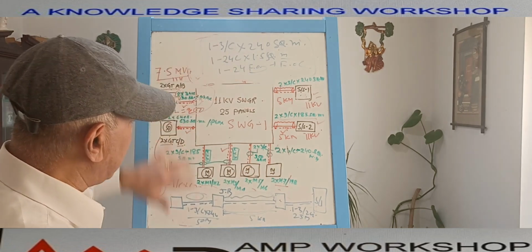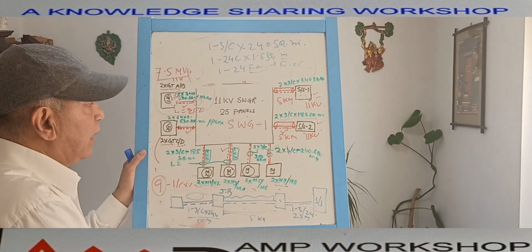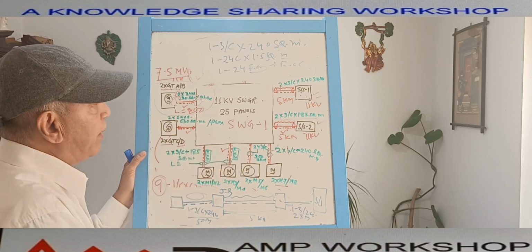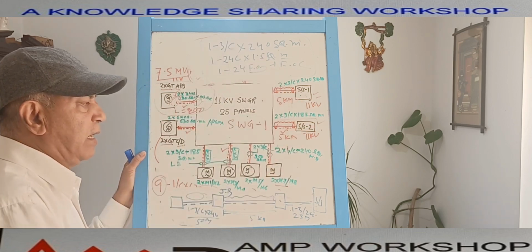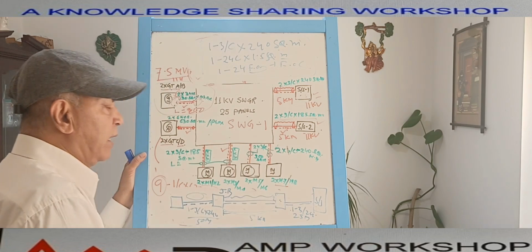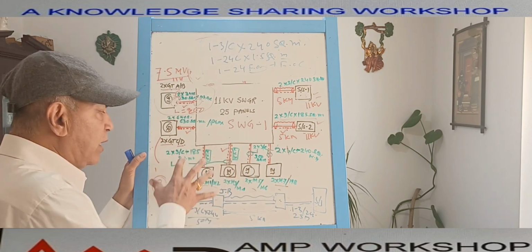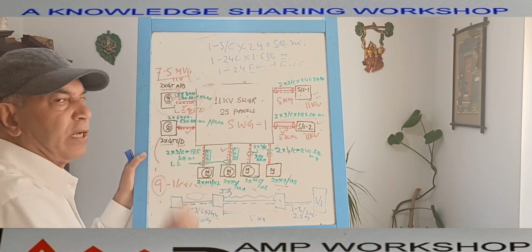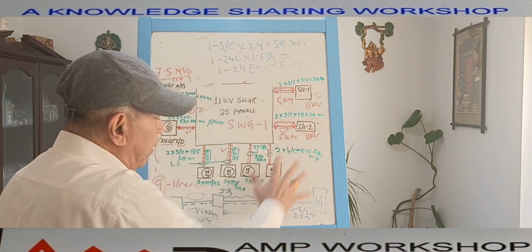So from this diagram, if I develop this block diagram in this way, immediately from the block diagram I can make out how many cables are there, what the various sizes of the cables are, how the cables are laid, what the length is, what the cable tag is, and how many equipments there are for the switchgear. So this is the 11 kV cable block diagram.